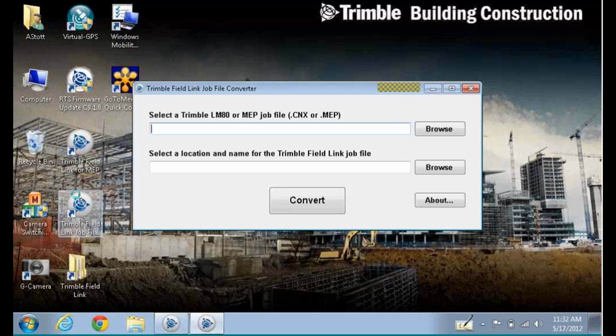File size, it really depends on how clean your file is. If it's real simple lines, there's no duplicates, yeah, it's going to handle a bigger file size. I recommend try and keep it right around 5 megabytes or less. Again, it depends on how much stuff you've audited and purged out of your CAD background, depending on how big the file size. To me, it's not so much a file size as it is a speed issue.